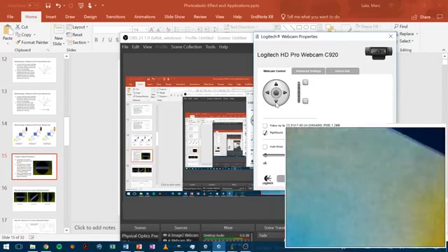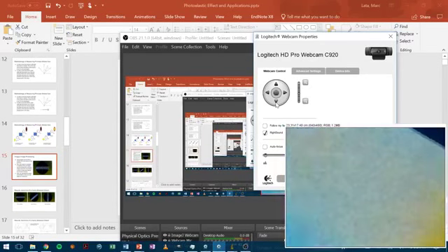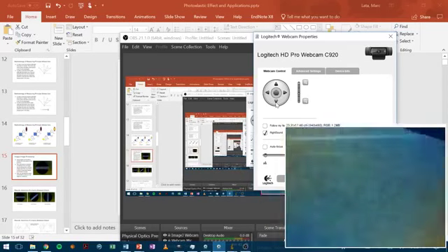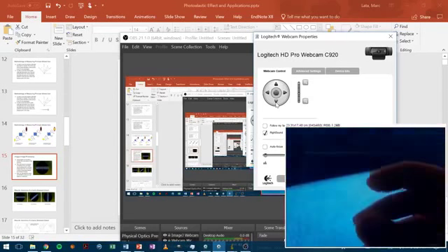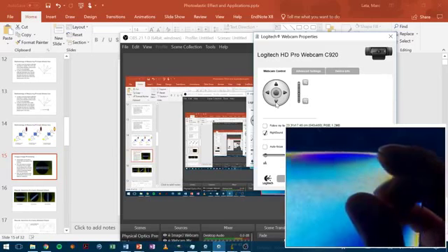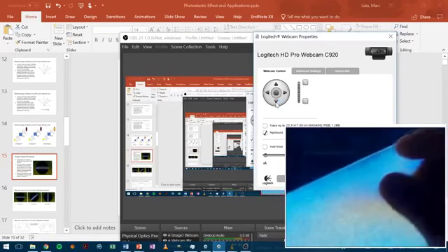You can see that the stress in this object is essentially uniformly linearly oriented, because it's either entirely isochromatic or entirely isoclinic. As you bend it, you start to get the colors, and if you bend it a lot, you start to see all the different fringe colors show up. So it's pretty neat.